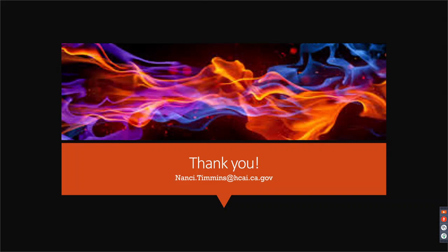ICC has another one. I'll try to look up the name here if I remember what presentation I put it in. They have a resource where you can look at what they call archaic construction, which is kind of funny because what they consider archaic is pre-1950. I'm like, that's not nice. That's not archaic. But anyhow, they have a resource for what they call archaic construction and some equivalencies that you can look at. You can look at 721, the back of chapter 7, sometimes forgot about. Look at those tables and see if some of your conditions match similarly to that.